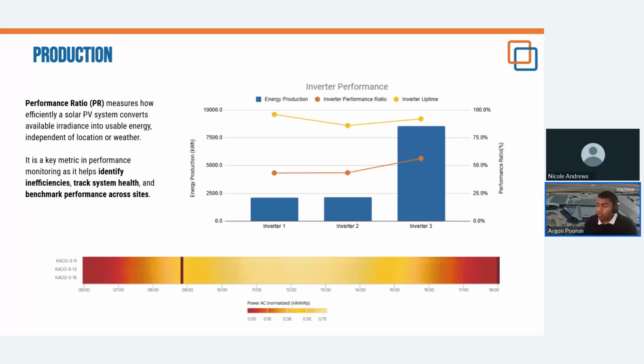You can also start to identify impacts if you look at this heat map from day to day and month to month to understand if there is a degradation, for example thermal degradation in the inverters over time. If you have access to the inverter temperatures, that's also a good thing to look at.